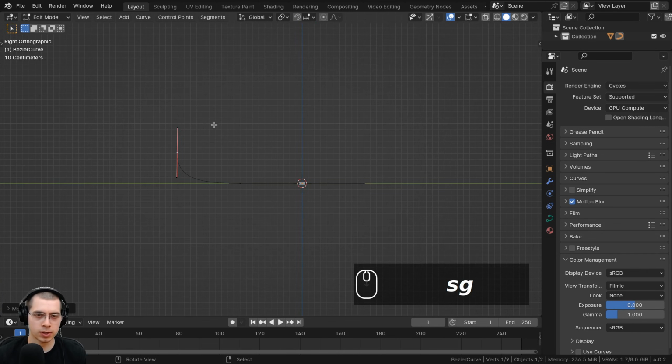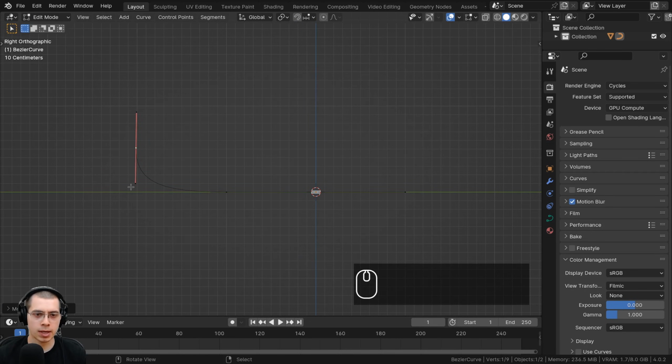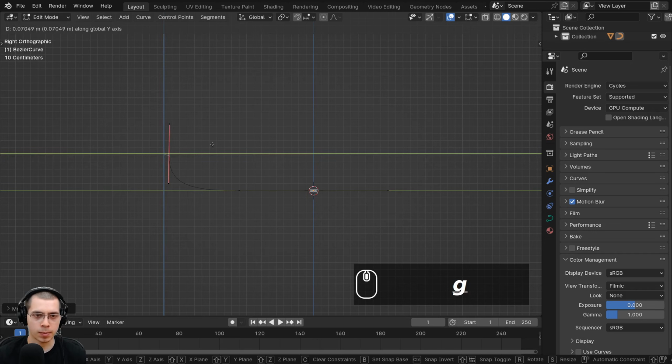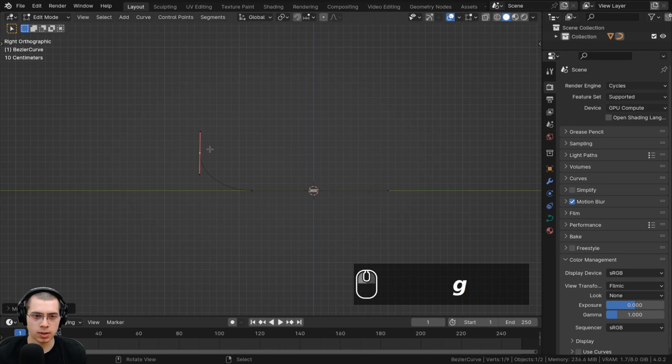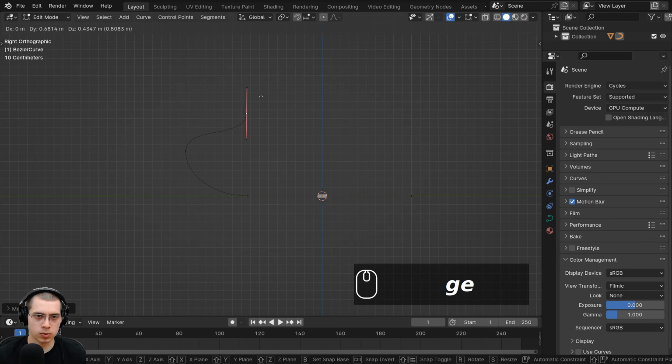And you can see there are little grids in Blender, and I want to make it about 3 grids long. So I'm going to actually bring this back a little bit. It's going to be about 3 grids, so 2 grids in the center, and then half of this grid and half of this grid. So about that big. E to extrude, bring that there, and then rotate that over, just like that.